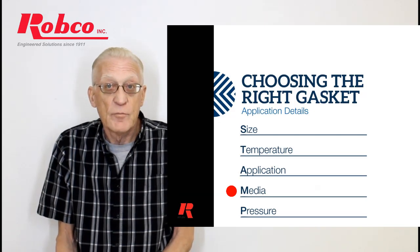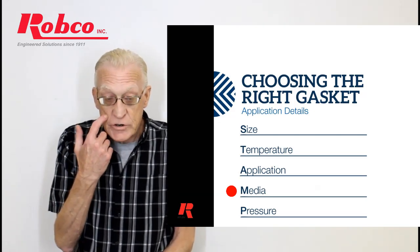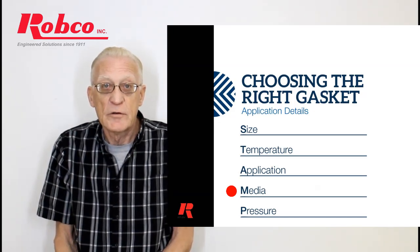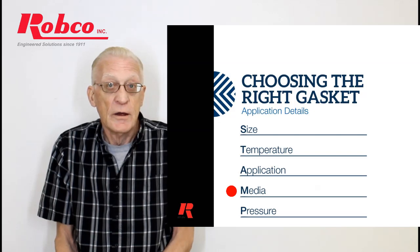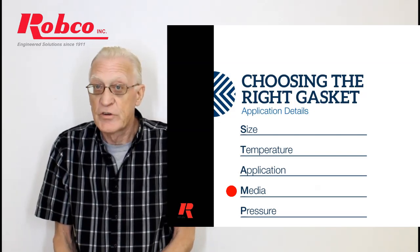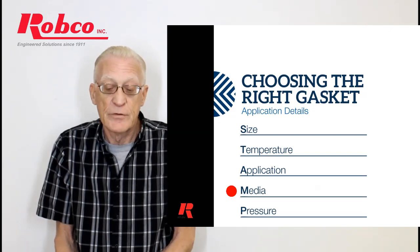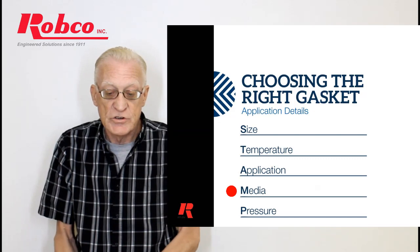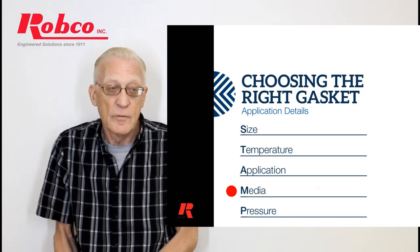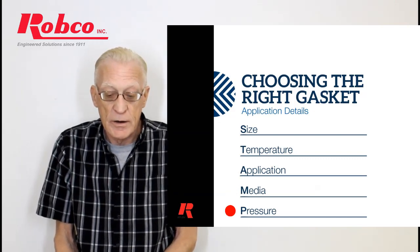Media, of course, is the chemicals, is the water, is it sulfuric acid. Concentration of that is very important. I'll repeat it a couple of times, but sulfuric acid at 100%, you can put your hand in. At 96%, with the 4% being water, it'll eat your hand off. So concentration and what else is in the mix is extremely important to be compared to whether that gasket will do the job or not.